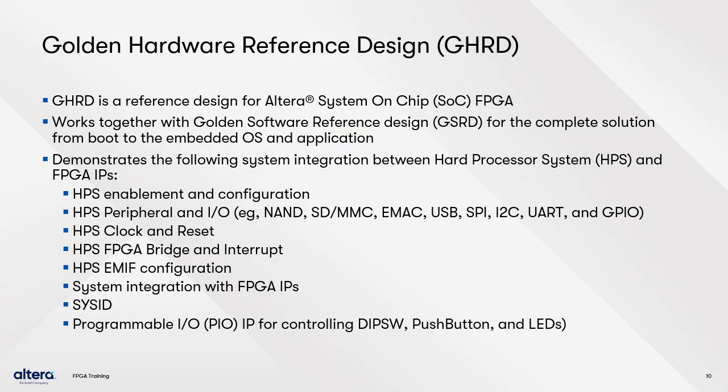The Golden Hardware Reference Design, or GHRD, is a reference design for Altera SoC FPGAs developed and maintained as part of a complete solution to boot to an embedded OS and application inside a Golden System Reference Design. The GHRD provides a reference design that demonstrates the system integration between the HPS and FPGA IPs. For further information, you can go to the GitHub repository provided in the resources or to rocketboards.org.